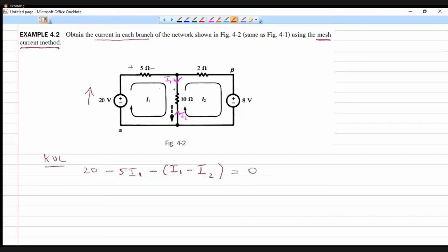Have we completed the loop? We have covered the entire loop. So after that, we will reach where we have started. KVL says that sigma of the voltages is equal to 0. So, I1 minus I2 into 10. Yes, sir, into 10. I forgot that. Is equal to 0. Now you can rearrange this and express in terms of I1 and I2 so that you will get one simultaneous equation. That you can label as the first equation. So this is for loop 1.